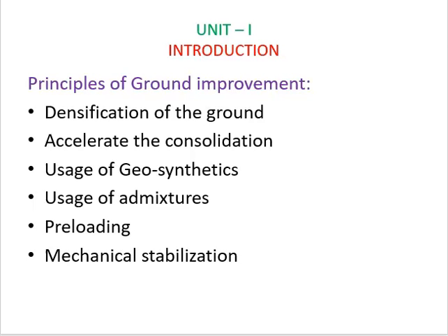Next principle is preloading. The purpose of preloading is to minimize the post-construction settlement. Before starting the construction, the weak soils at the site are improved by applying some static load for a long duration.